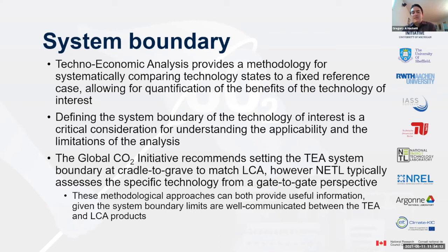One of the slight differences is that the Global CO2 Initiative recommends setting the TEA system boundary at cradle to grave to match the LCA, while NETL typically assesses the specific technology from a gate-to-gate perspective, where we really dive down into the technology itself. This is of relative importance. It can change depending on the technology that you're looking at. It might be important to look at how the carbon is captured, what the source is, and the purity. So it might be important to expand the front end from beyond the gate to the cradle. But typically we focus on the technology itself. So that'll be something that we iron out right up front.